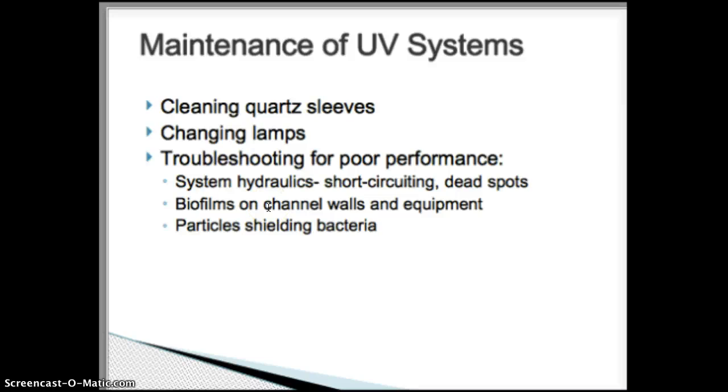Maintenance of UV systems. Cleaning of the quartz sleeves is very important, and we've already discussed that. If they get cloudy or fouled, they're not going to be as intense and they're not going to be as effective. Additionally, changing the lamps as well. All of these maintenance procedures would be on a schedule, on a timed, planned maintenance system. And then troubleshooting for poor performance.